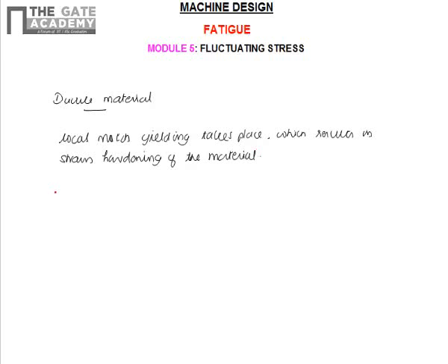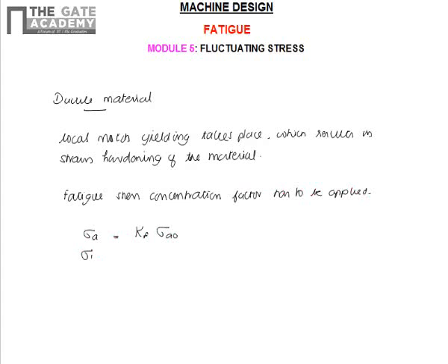Now for ductile materials, in the presence of a notch, the fatigue stress concentration factor has to be applied, and now sigma a becomes Kf into sigma a0, and sigma m becomes Kf into sigma m0, where sigma a0 is the nominal stress amplitude or amplitude component of stress, and sigma m0 is the nominal mean stress.